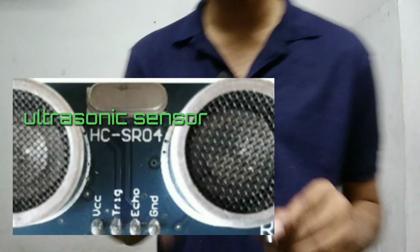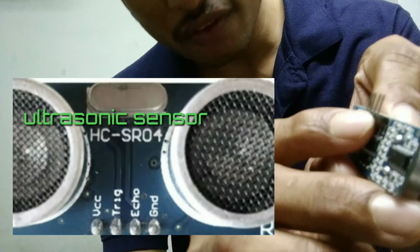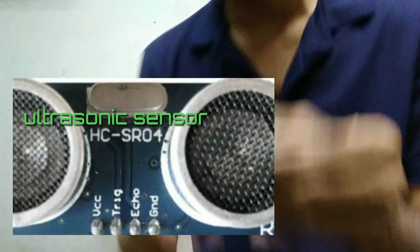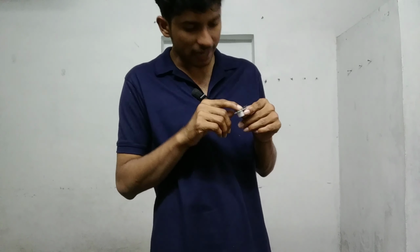Coming to the next sensor, this is an ultrasonic sensor. The ultrasonic sensor consists of 4 pins. The first one is VCC, the second one is the trigger, the third one is the echo, and the fourth one is ground. We should connect the VCC pin to the 5V pin on the Arduino board, and the second one is the trigger.